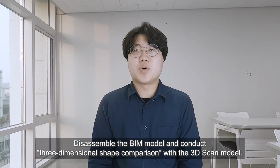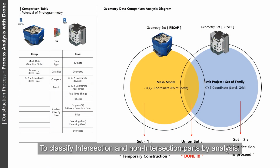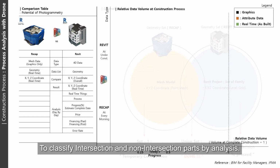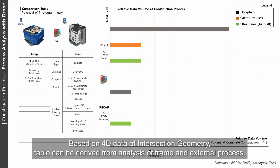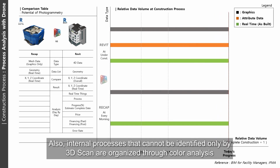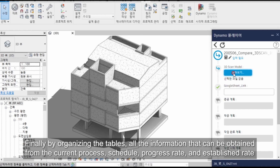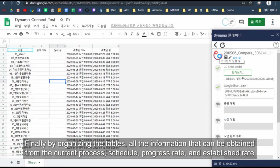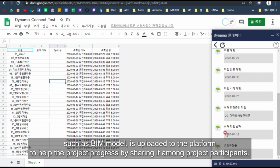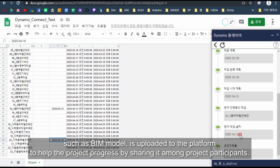This assembles the BIM model and conducts a 3-dimensional shape comparison with the 3D scan model to classify intersection and non-intersection parts by analysis. Based on the 4D data of intersection geometry, a table can be derived from analysis of frame and external process. Also, internal processes that cannot be identified only by 3D scan are organized through color analysis. Finally, by organizing the table, all the information that can be obtained from the current process, schedule, progress rate, and established rate from the BIM model is uploaded to the platform to help the project progress by sharing it among project participants.